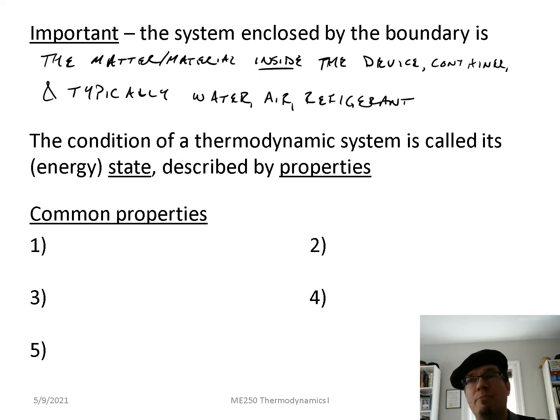Again, you can apply thermodynamics to anything. You can apply it to lead, you can apply it to plastic, you can apply it to any matter, silicon, etc., etc. Typically, mechanical engineers are going to be working with working fluids of water and air or refrigerant. And typically, when you're dealing with control masses and control volumes and thermodynamics, you're taking the device as a black box and considering what it does to the matter inside of it, to the system inside of it, to the working fluid inside of it.